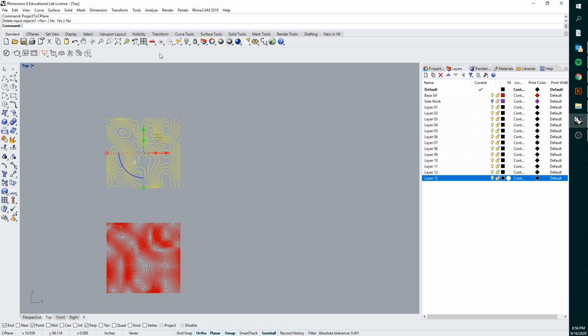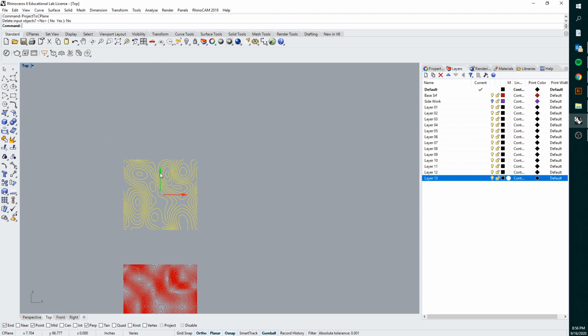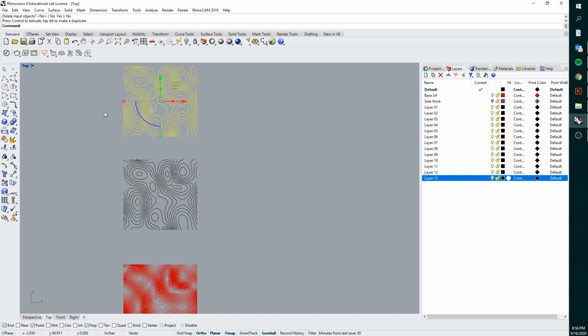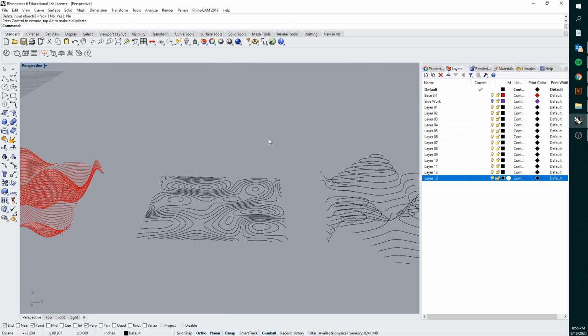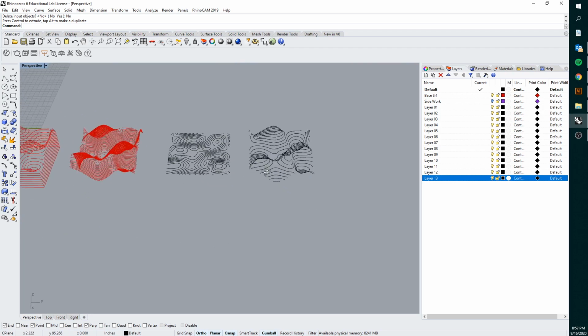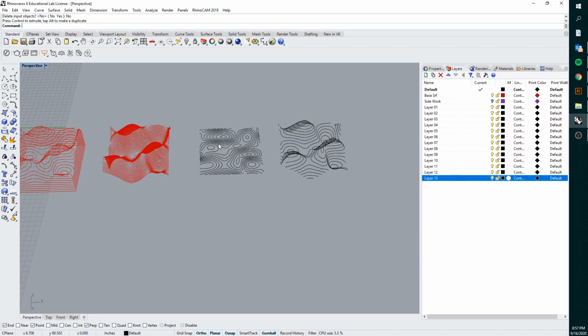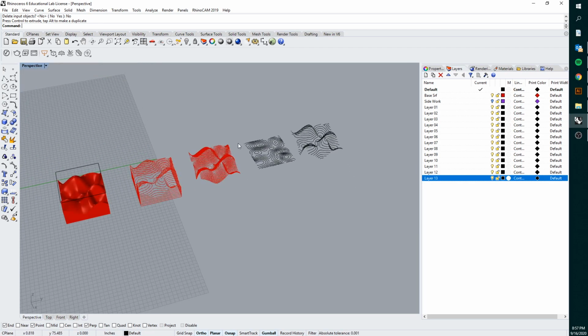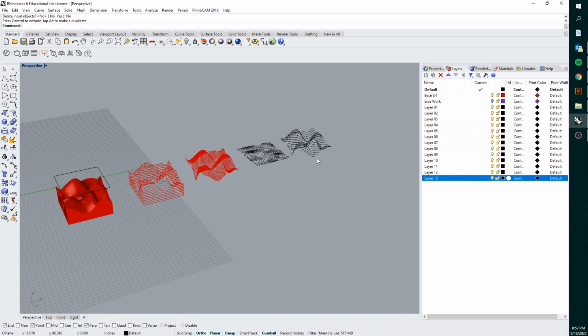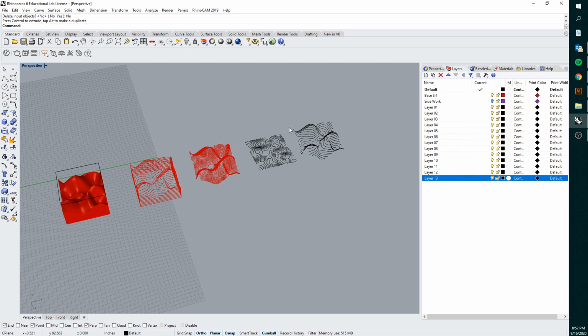And then once the command is complete, without clicking off of anything, just grab the geometry and move it off. So you can see that we now have a copy. And what that copy is, is a totally two-dimensional drawing of these lines that you've created. So if you need to add topography or contour lines to your plans or something like that, this is a really good way to do it. Grab the contours, bring them over off to the side, do a project to C plane or a make 2D to make those totally flat for your drawing.